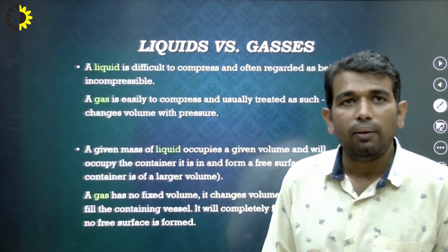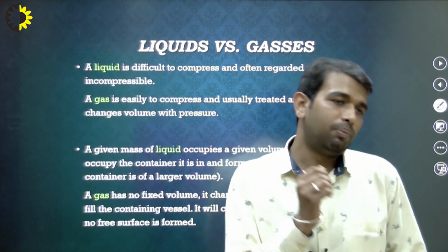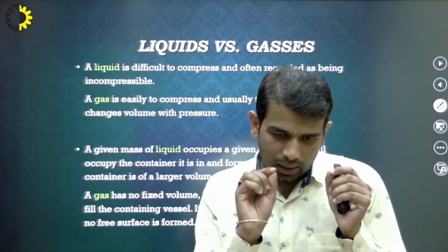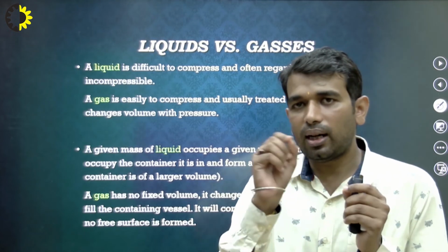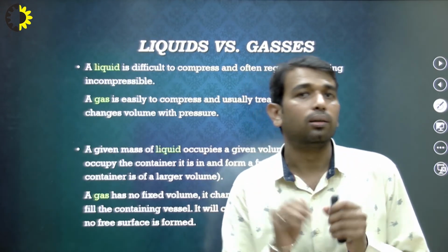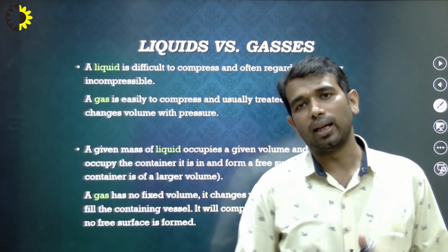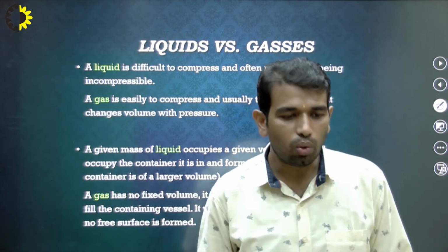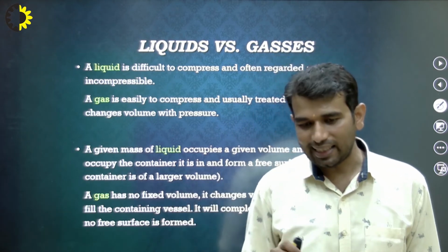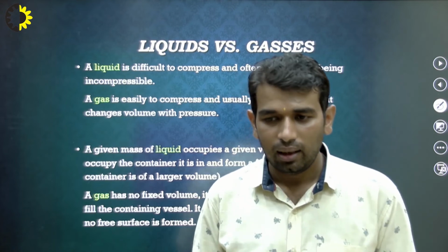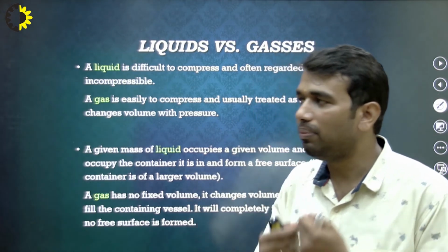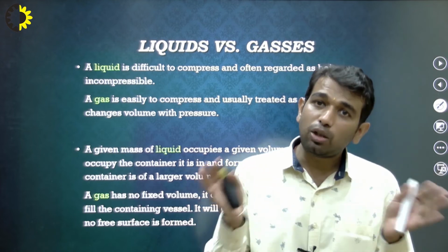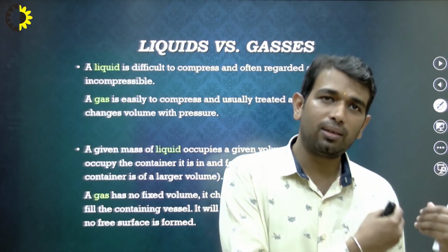In liquids, when you start increasing the temperature, the viscosity starts reducing. But that is not true in the case of gases. When you deal with gases, things are quite different, because the molecular collisions in gases start increasing, and because of that, when you increase the temperature in gases, they offer much more viscosity compared to the previous temperature condition.